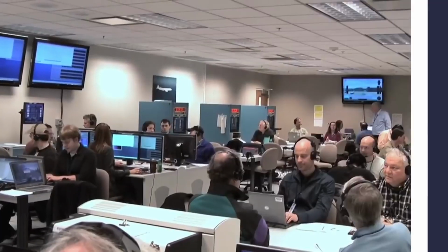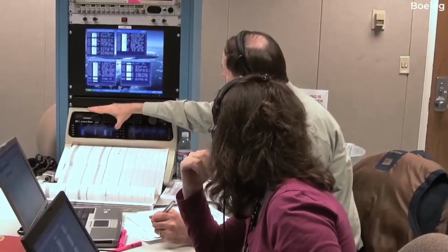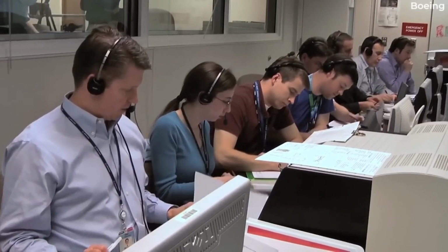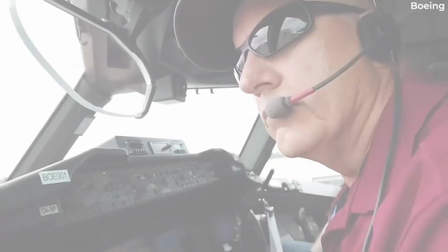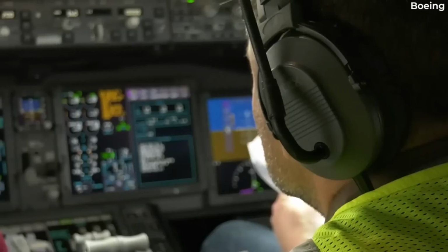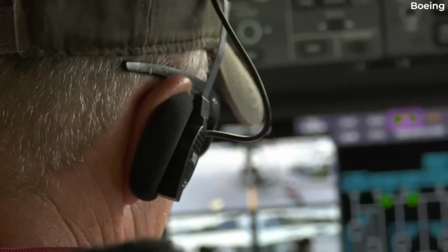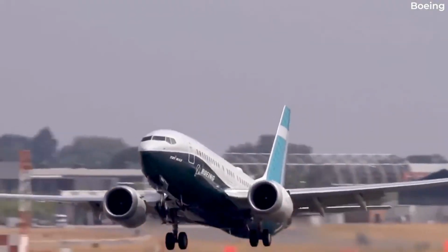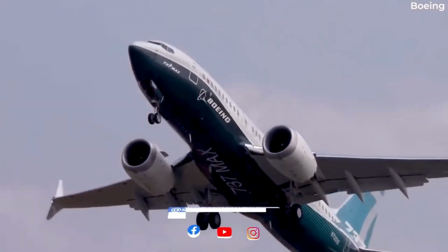The required record review start date varies depending on the age of the aircraft. However, once initiated, the repetitive inspection intervals are not to exceed 7 years. The certificate holder must make both the aircraft and the records available to the FAA for inspection and review. The certificate holder must notify the administrator at least 60 days in advance of the availability of the aircraft and the records for review.